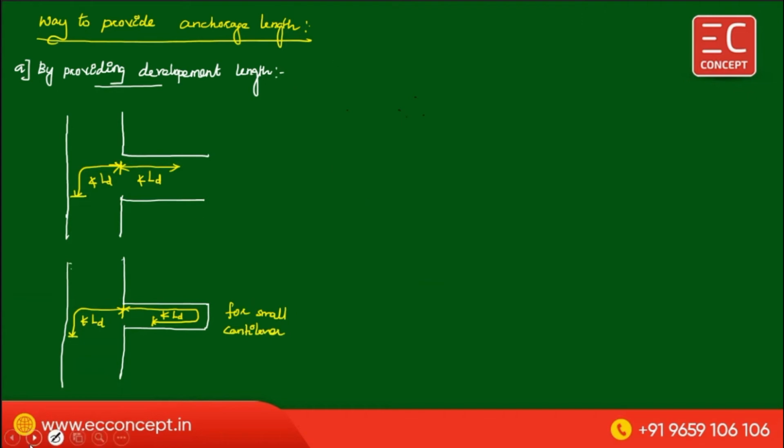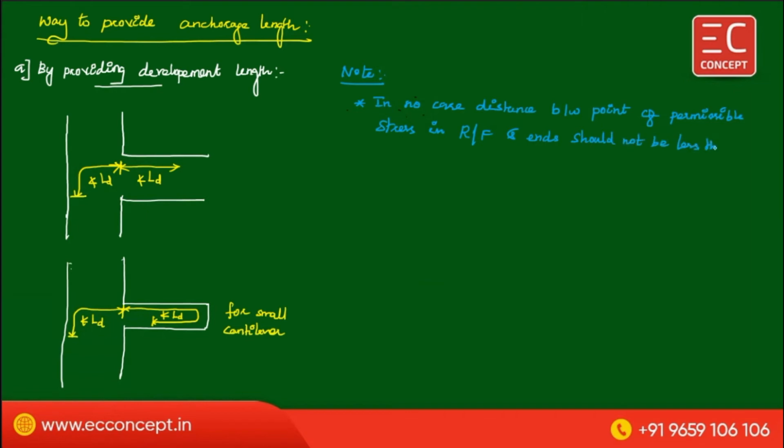Then note, we have to write some note points. Note, in no case distance between point of zero stresses in a reinforcement and ends should be less than LD.